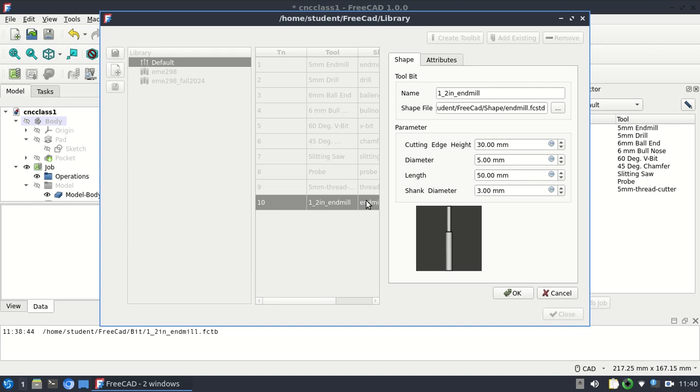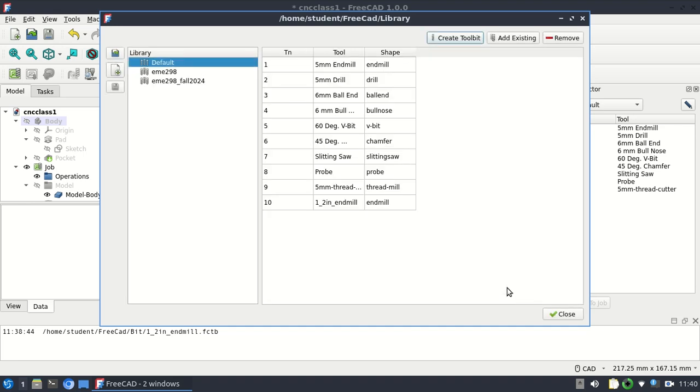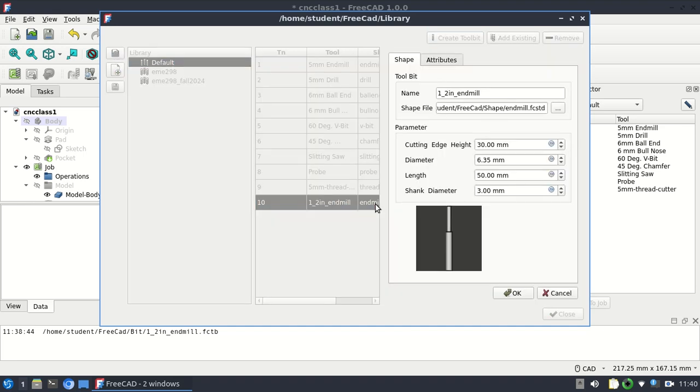the diameter. So we're going to use a 1/4 inch. So to use a 1/4 inch, I'm going to do 0.25 space IN. Okay. If I double click there again, it filled up with 6.35. Or you can just put 6.35 now that we know. Computers. Right? Good? Everybody there? All right. Okay.